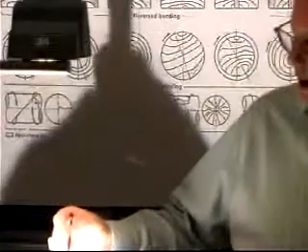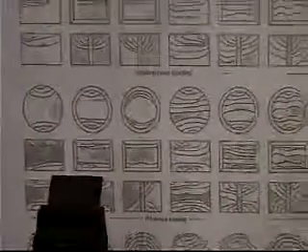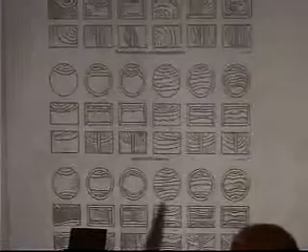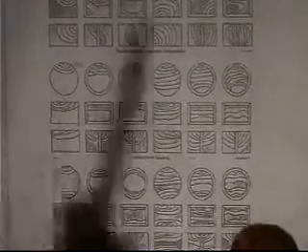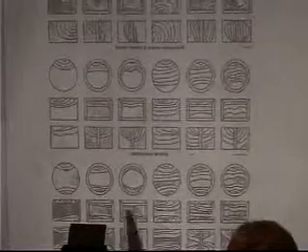Well, if you're bending it back and forth, you should get a fatigue crack that starts on both sides, okay, because you're going both ways. If you're only doing unidirectional bending, if it's just bent down and comes back up, then you're only going to get a fatigue crack starting on one side. So if someone brings you a broken bolt, you ought to be able to look and see whether I've got a fatigue crack on one side or both sides.